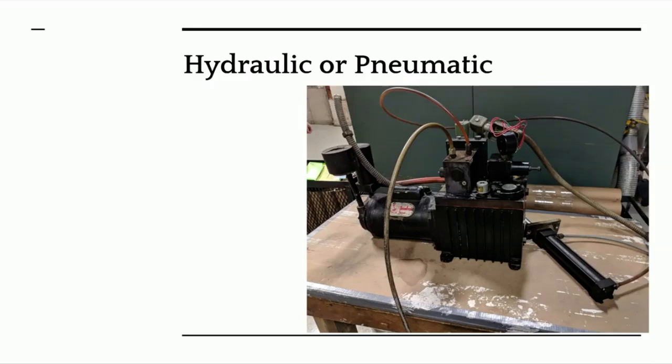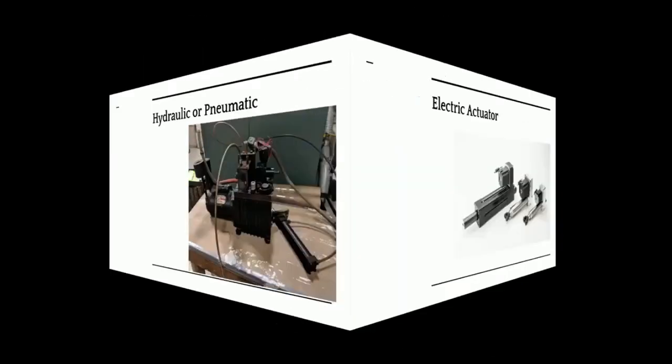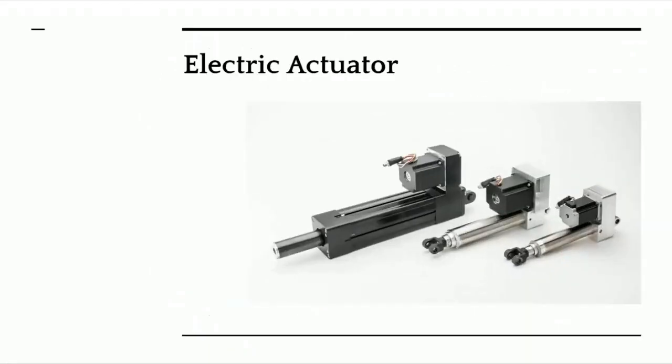You can see them. But the problem is maintenance. You need to balance the valves, change the filters, and they could cause leaks, and this could contaminate your product. And then the precision and accuracy that you can get with an electric actuator is not something that you can expect in a hydraulic actuator. So most web guides nowadays are going to use electric actuators.